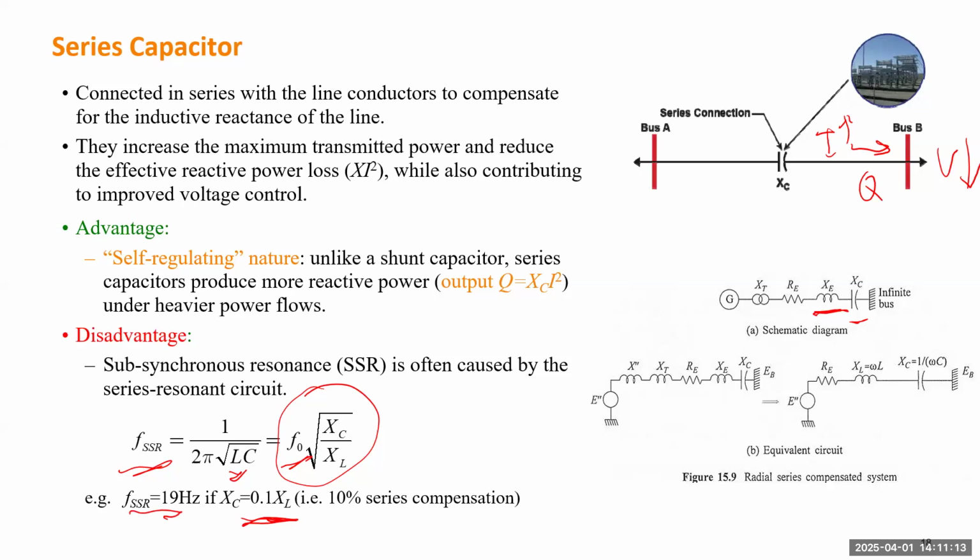This becomes a more significant issue, especially for wind farms, because a wind farm is usually built far from any city, where you have very rich wind resources. But when you want to deliver the power, you have to build a long transmission path, and the total reactance will limit how much power you can deliver safely.